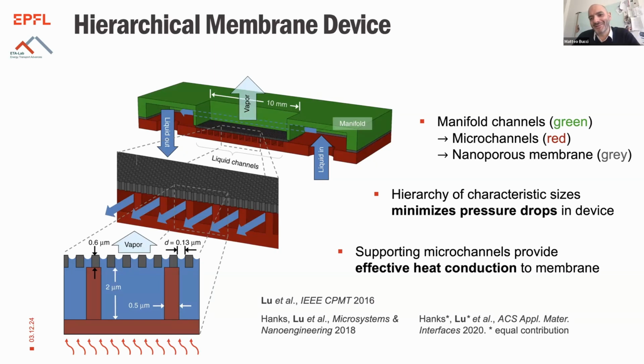I have a follow-up question, Alessio. Please go ahead, Matteo. So what is the mechanism of failure here? Is it dry out or nucleation in the liquid channels? I think in our case, what I suspect is the way we designed the channels, they have a dead point in the center where you expect the velocity to be close to 0.